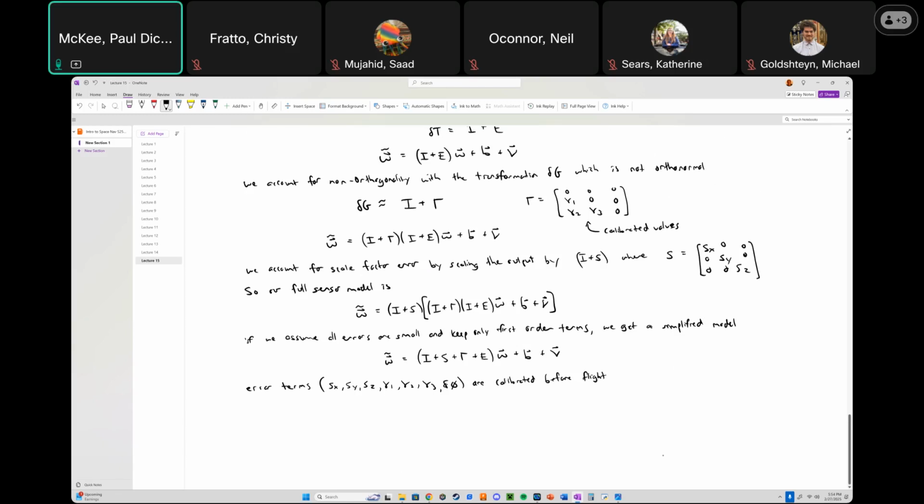And the bias is estimated as another state. So remember, we learned the trick about if we have some parameters which are kind of annoying, which for whatever reason we can't afford not to know, then we treat that as part of the state. So on a real navigation filter, it's got position, velocity, attitude. It's got things that you would expect to see, but then you'll also be tracking loads and loads of these little bias and error terms here and there, which kind of have to come along for the ride or else the whole filter won't work.